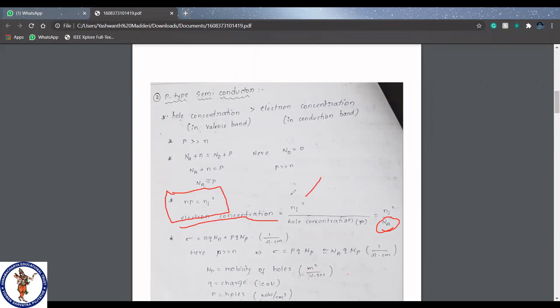In a semiconductor bar, if I am talking about a p-type semiconductor where the hole count is higher compared to the electron concentration, the majority charge carriers are holes and the minority charge carriers are electrons. Not every time, but in most cases, we will use this formula just to find minority charge carriers. In the p-type, it is the electron concentration, found by using the hole concentration.